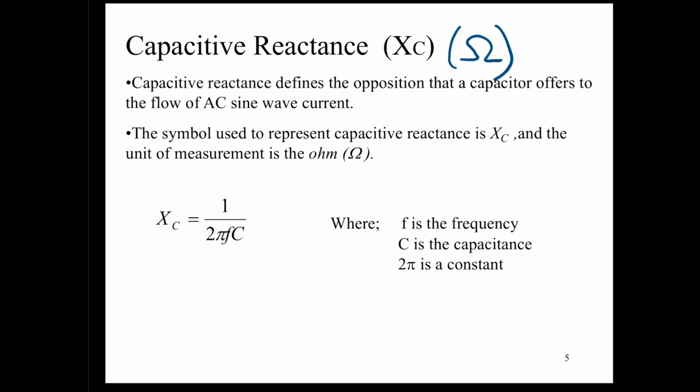So that often becomes, for a beginner, a little bit of a challenge, but you have to be aware when you're working with capacitors, are you working with their capacitive value that is determined by its physical properties and gives you a value in farads, which doesn't change with angular velocity or frequency?